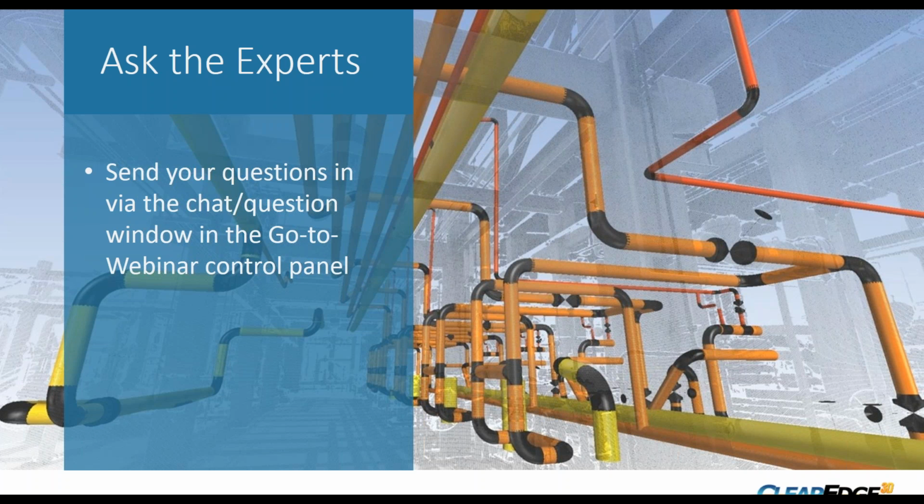Control on job sites is something that's going to be plus or minus ½ inch to an inch. If the control is that far off, then all the tolerances in specification manuals are based off the control, not off the absolute physical location in the universe, if we had perfect measuring tools. So it's a layered and complex thing, and navigating that with clients can be challenging.